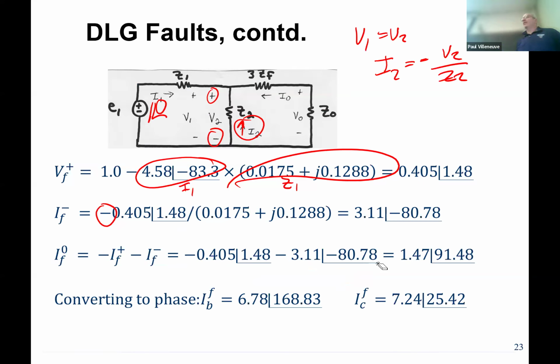But I did a project for an Air Force base. I think it was an Air Force base in Connecticut, that they actually had a higher level of double line to ground fault current than single line to ground. That's the only time I've ever seen that. But it was a pretty neat, unique system down in Connecticut. They had really odd, or not odd, but different values of negative sequence impedances that I hadn't typically seen.